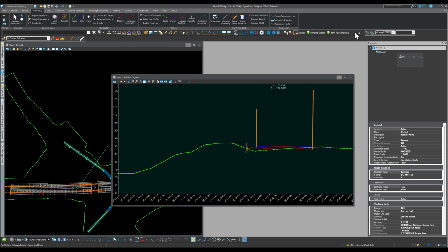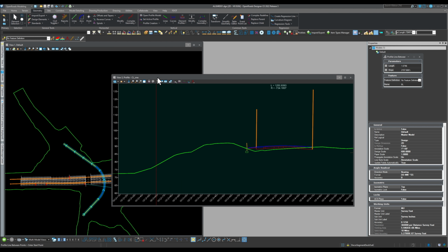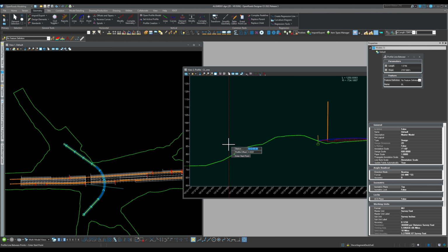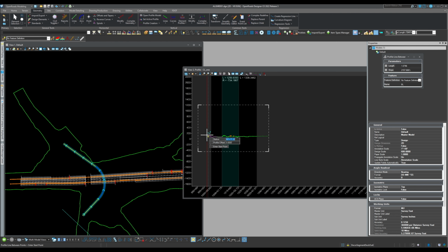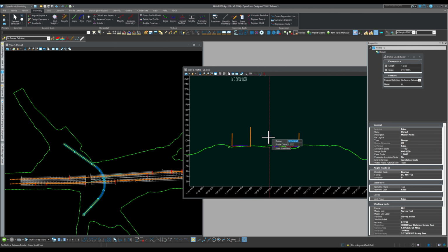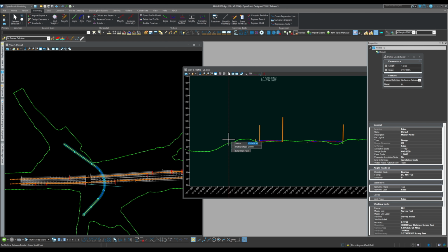Let's fire up this. And then let's get profile offset. Here we go. So fire up the Civil AccuDraw and then go to this option, the profile offset. So now let me show you the 2D. As you can see here, my tool is moving. As you know, my alignment starts from here till here, literally. But I only care about this area, right? But I want to start at specific stations, for example. So that's how you do it.